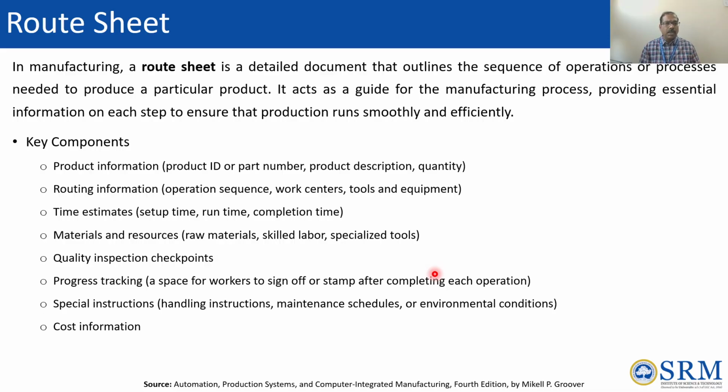How we are going to do the quality inspection, wherever we are going to do it, whether at each and every workstation after completing the particular manufacturing or machining process, or at the end. Like that, we need to have a checkpoint. It depends on what kind of product design we have. So it is very, very important, and it should be decided in the beginning itself.